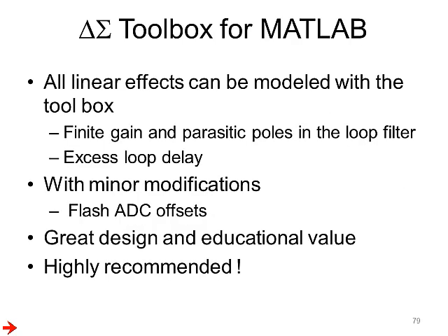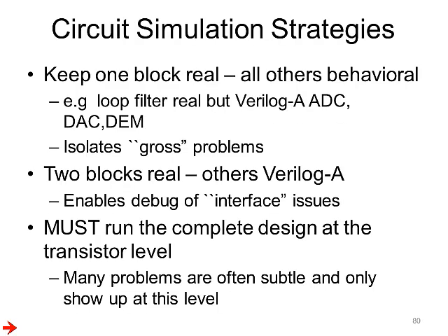Overall, all linear effects can be easily modeled with the toolbox, and with minor modifications, even non-idealities like offsets in the quantizer, etc., can be modeled. It's a great tool which lowers the barrier of entry to delta sigma modulator design and understanding, and is therefore of tremendous educational value also, and I'd highly recommend it.